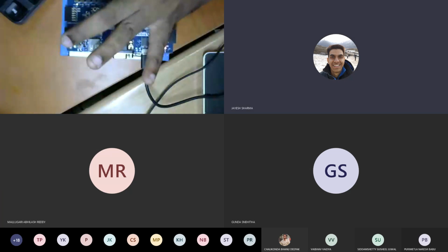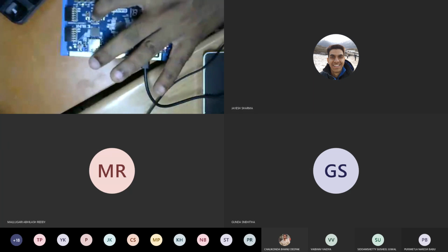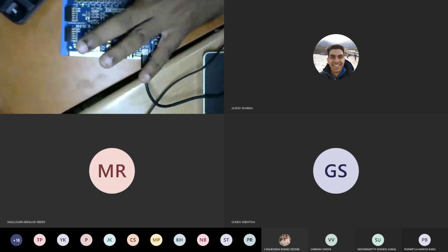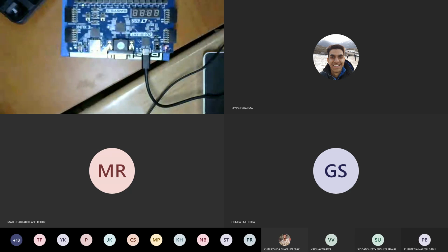So now if you see again, if the reset equals 0 and the clock comes, the output should be set to 0. I'm just giving the clocks, but reset is active now, so it should be 0. That's the behavior we are checking here.